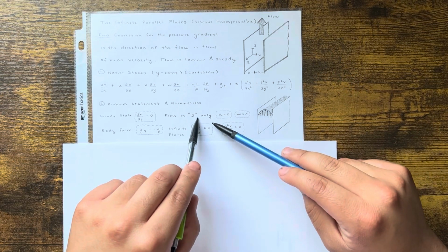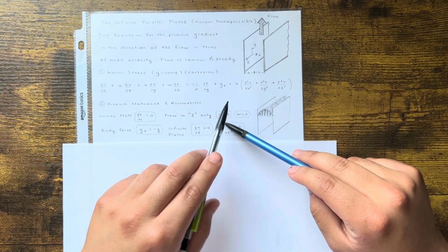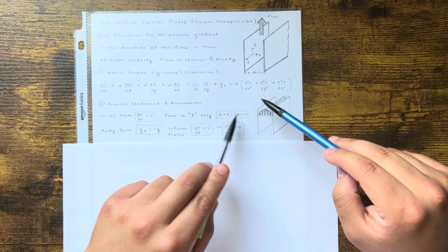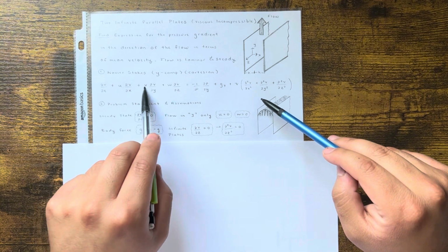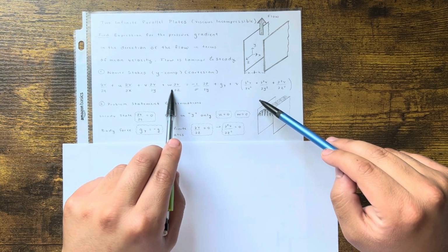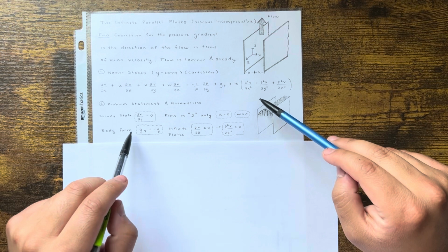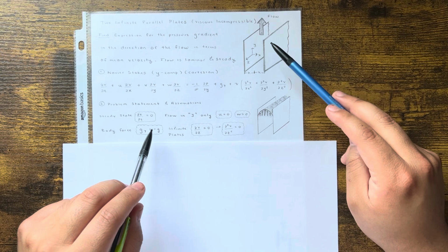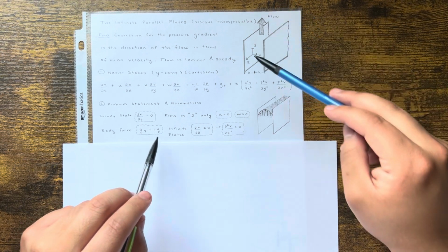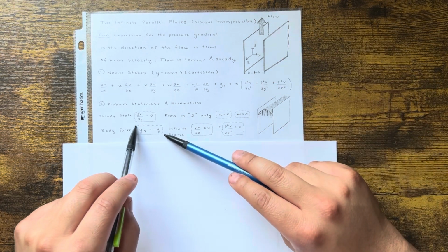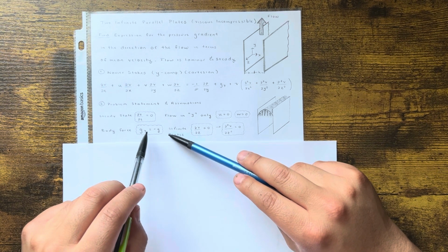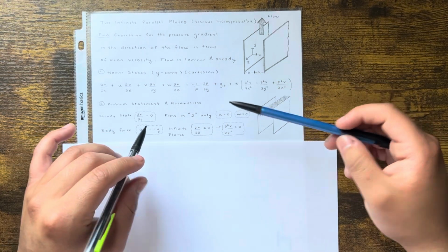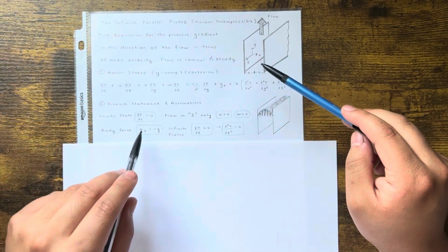So the flow is in y only, okay? So u, which is the x component, velocity in the x, velocity in the z is 0, okay? So just like that, that term goes away, u, and then w goes away, boom. The body force, okay, that's just what I just said right now, that there's only gravity acting on the system. There's something pushing it up, but in terms of body forces, there's only gravity, okay? And because it's in the y component, you have a -g. All right, sometimes it's at an angle, so you got to get like sine theta, cosine thetas. But in this case, it's going straight up. So it's just -g, okay?